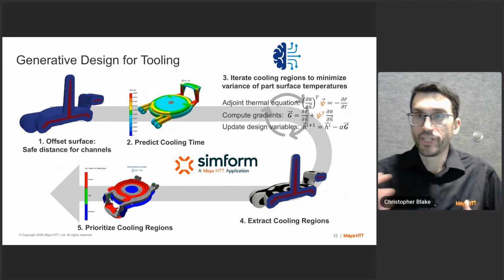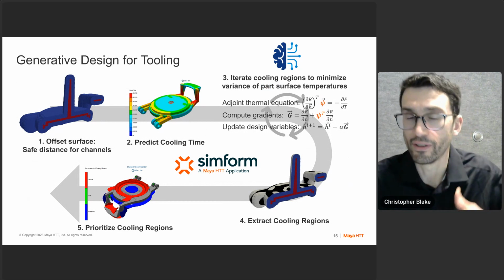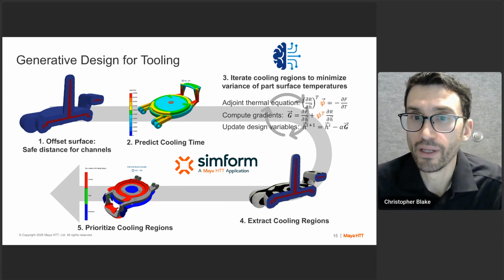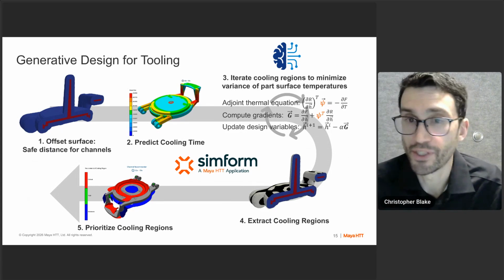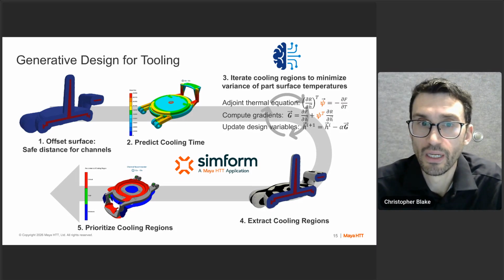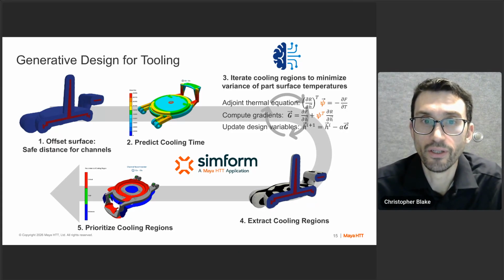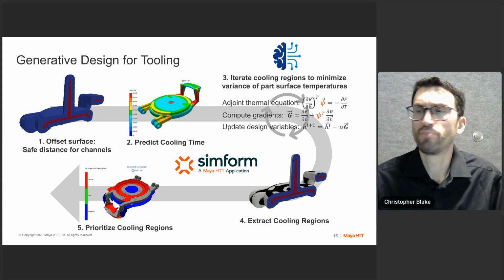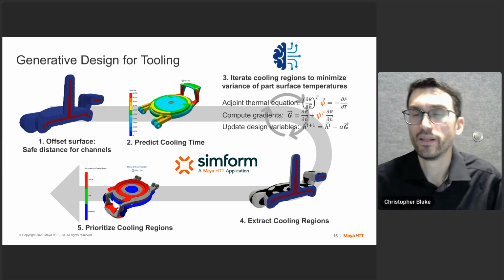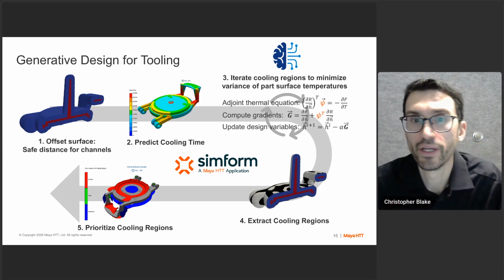So referring to generative design, generative algorithms aren't limited to producing reports or generating images. There also exist capabilities to produce three-dimensional designs. Maybe you've heard of the term topology optimization. That's one of those technologies that you can use to produce those really organic looking structures, like for brackets, that meet the strength requirements, but also minimize the mass of the part.